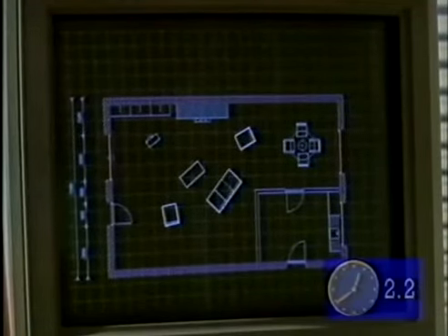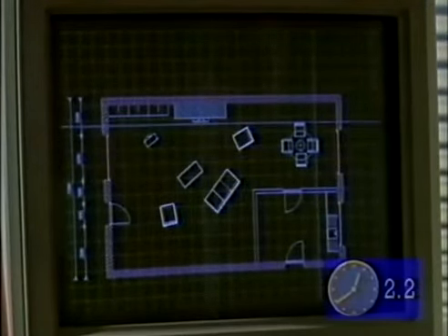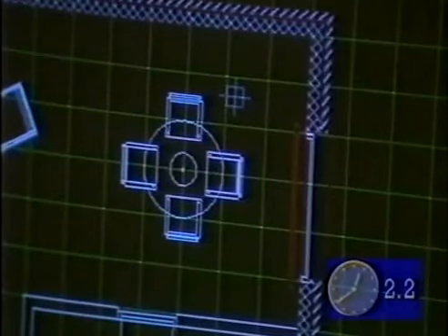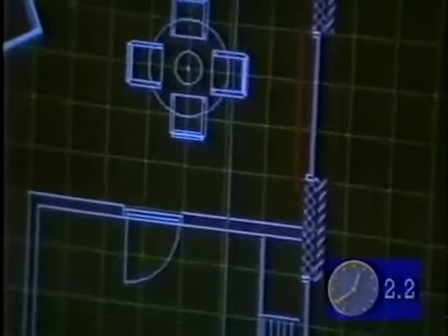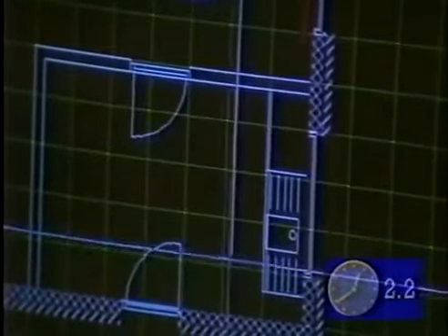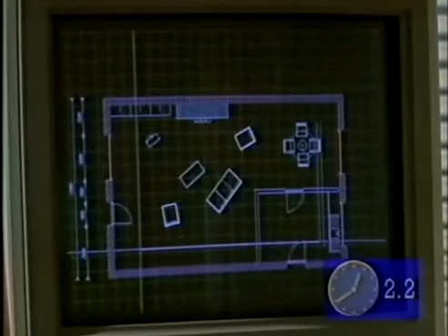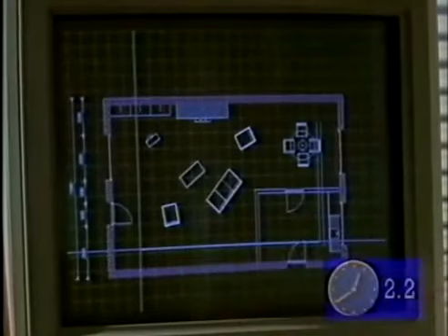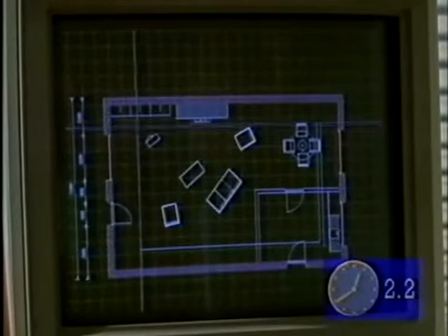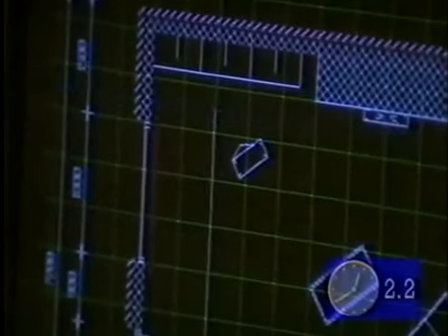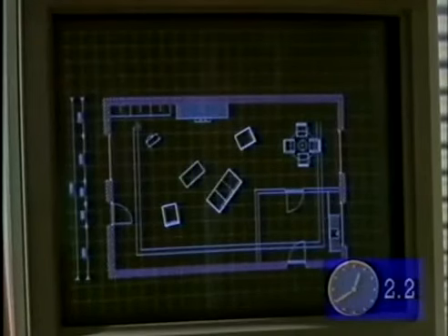I now want to move to a particular location, so let's start up here. I can then issue the J command again, and whenever I go, let's go down to there, it is going to generate me a line. I can then go to there, and as I've given it a second angle, it has put in the first parallel line and also mitered the corners automatically. So again, I could come up to here to issue that line. I can then come out of that, and again the last line will be put in.